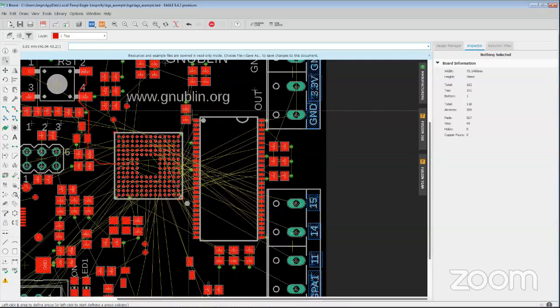I've never seen a manufacturer do multiple copper weights on the same side of a board. But remember that a polygon is basically a sheet of copper, so the width that you assign it isn't really critical. Basically, there's an inverse relationship between width and resolution. The lower your width, the more resolution in which the polygon is drawn. So our typical recommendation for polygons is to use the biggest width you can get away with. That way you generate the smallest amount of data.